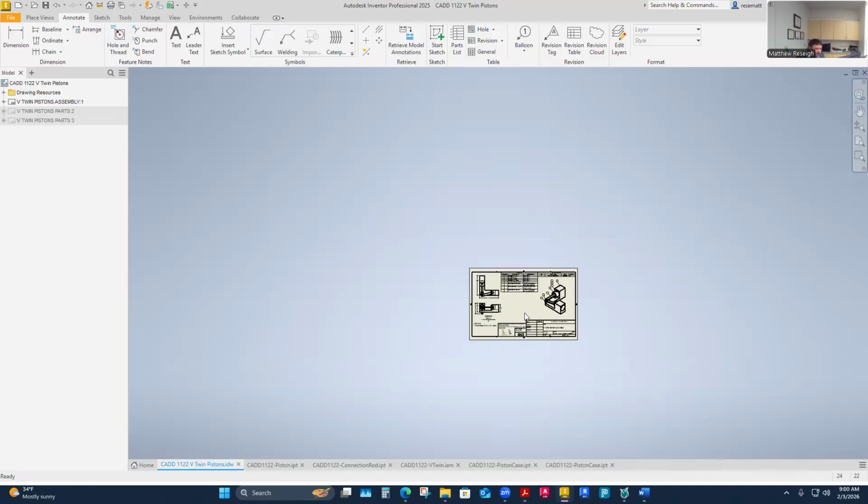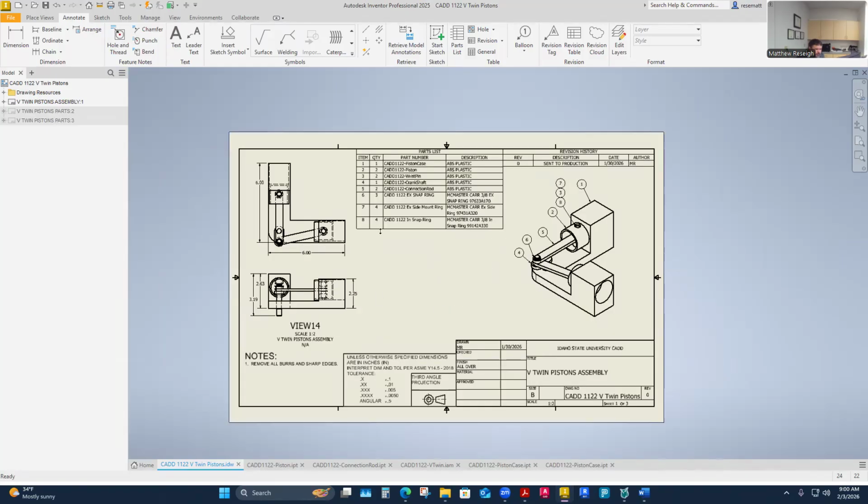There are reasons why sometimes you have sheets that you wouldn't put as part of a normal print pack. You might have cut file sheets. Sometimes I have some supplementary sheets within my drawing packet that I don't necessarily print as part of a print pack. It's kind of a rare, weird thing. I'm trying to think of when I would do this. I know sometimes I would do stretch out patterns, like piping coping patterns. That's when people need to cut pipe for special applications. I can give them a flat pattern.